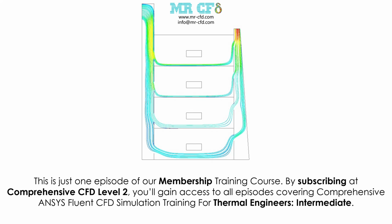Turbulent airflow enters the domain from the top left region, and due to the heat transfer to air from the right diagonal wall with a temperature and heat generation rate of solar radiation equal to 305 Kelvin and 1000 watt per meter cubed, respectively, conjugate heat transfer leads to buoyancy effect, which helps the airflow exit the domain from the top right region. This process creates a steady airflow in all four stories of the building. The Boussinesq approximation is utilized to simulate upward force on fluid due to the difference in density.